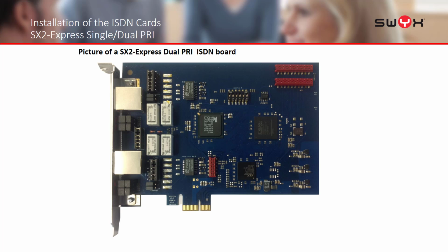With that jumper in place, this is a 30 channel board that allows power fail or failover in the case of a master standby scenario setup. There are no 120 ohm termination resistors, of course, because there is no bus mode on here, and we still have the clock synchronization sockets at the top there.